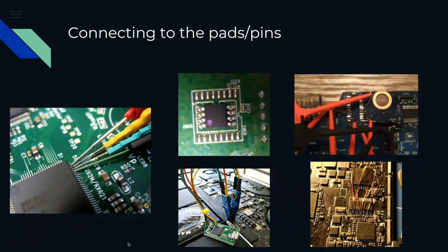So, connect to the pads. If you identify the pins and you want to interact with that chip itself to extract the memory, or make sure what you have there is the protocol you are expecting based on the datasheet, specification and device functionality, maybe you want to use a logic analyzer on it. On the left are the probe hooks.